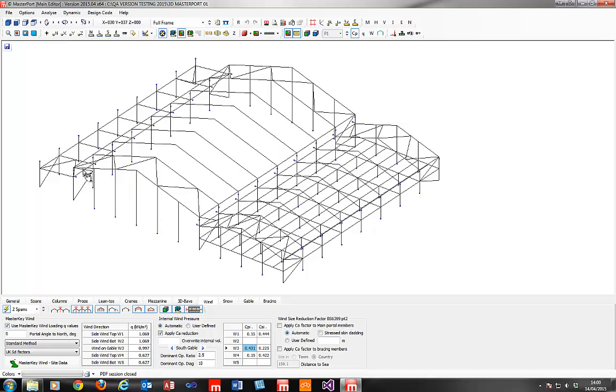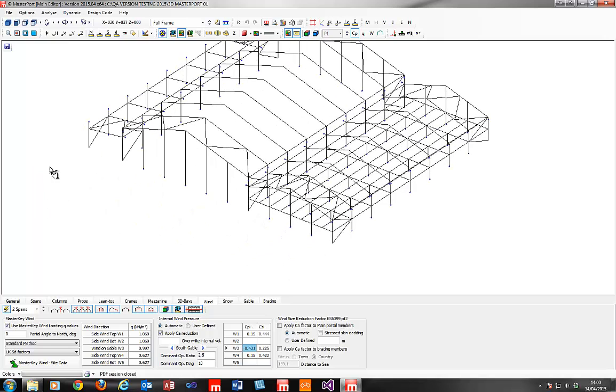So they might very well qualify for a size reduction factor equal to a wind diagonal, say from this point across to this point. Or you could argue that these ones might just be influenced by this portal frame here in itself if you wanted to be a bit more conservative. That's not something that was automatically taken into account in portals, whereas now we can do that.